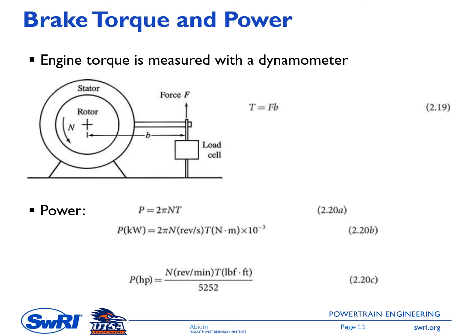So we have a rotor that is coupled electromagnetically or hydraulically or by mechanical friction to a stator here. So we have a rotor, we have a stator, and then the stator is balanced with the rotor stationary, and then the torque exerted on the stator, with the rotor turning, is measured by balancing the stator with weight, spring, or pneumatic means.